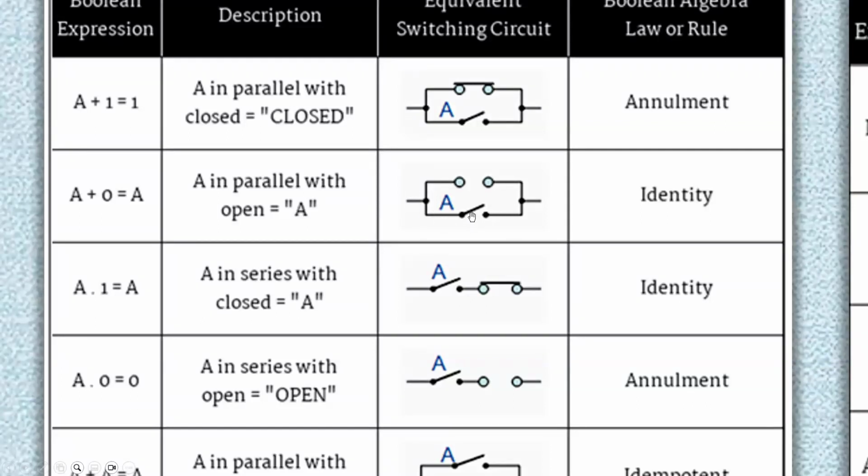So if this is true, remember, what is the PLC software asking itself when it sees a normally open contact? It's asking itself a question: examine if closed, because it's open. So see if it's closed, see if it's closed, see if it's closed, except it's asking itself that 1,000 times per second. So examine if closed, I'm just applying the ladder logic here as well. So that's the identity. When you see that expression, A or 0, it's always going to give you A.